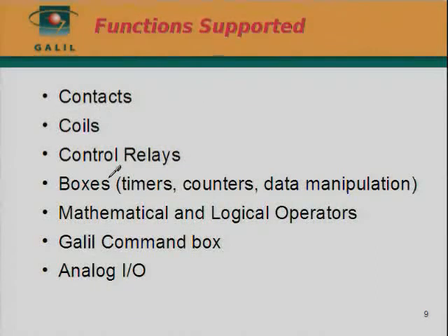Galil's ladder interface software supports numerous standard relay ladder logic functions, including contacts, coils, control relays, boxes such as timers, counters, and data manipulation, mathematical and logical operators, and analog I/O. In addition, there's a command box to send raw 2-letter Galil commands.